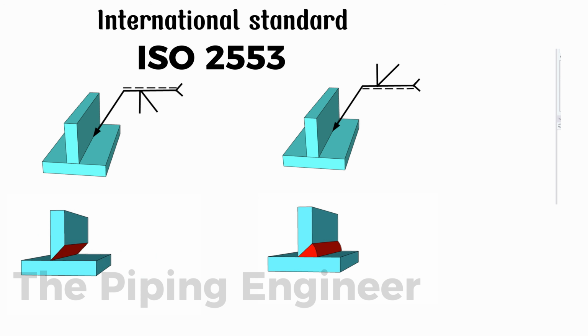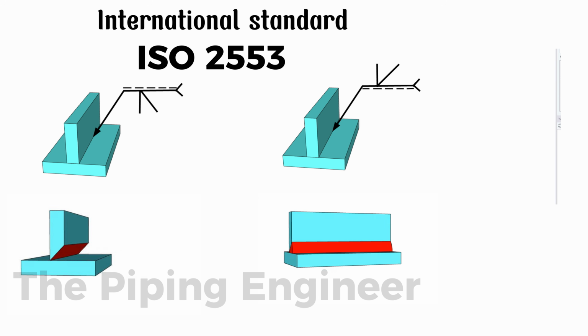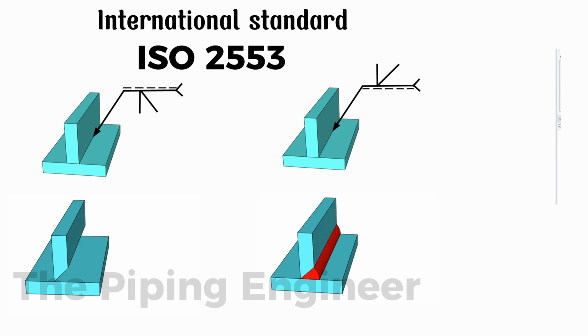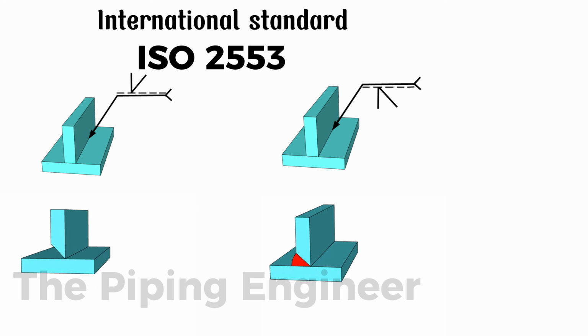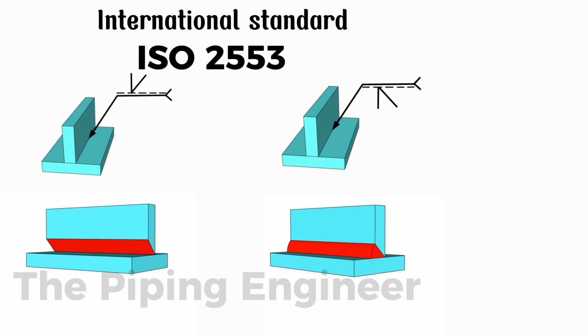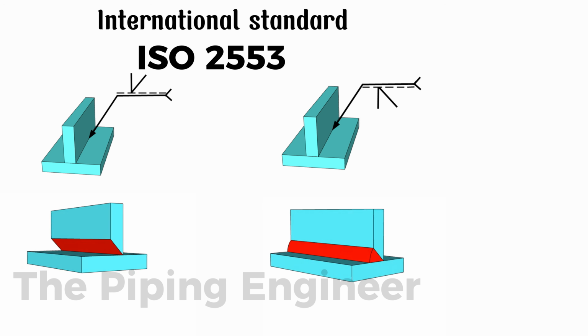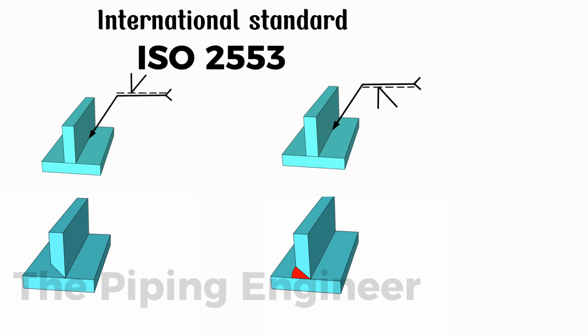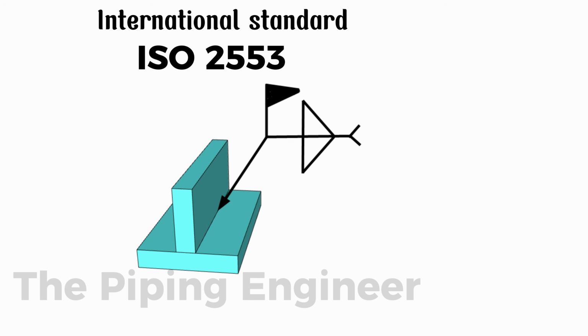Now, let's learn more about ISO 2.4 welding symbols specifically through the lens of bevel groove welds. When a bevel groove weld symbol is placed on the continuous reference line, it instructs the welder to perform the edge preparation and weld directly on the arrow side of the joint, the side facing the pointer. Conversely, placing the bevel groove weld symbol on the dashed, broken, reference line specifies that the edge preparation and welding must be executed on the other side, the side opposite to the arrow side, of the joint. When looking at engineering drawings, the site weld, meaning a weld that must be performed out in the field during installation rather than in the workshop, is clearly indicated by a small flag symbol located right at the junction where the reference line meets the arrow line.